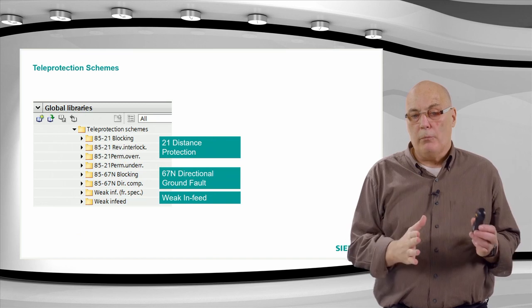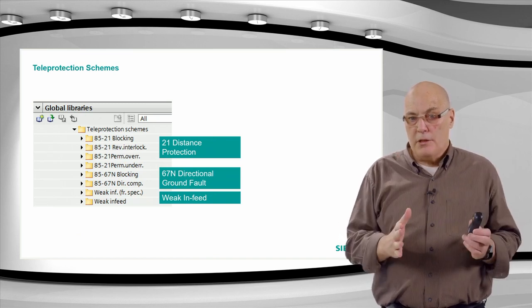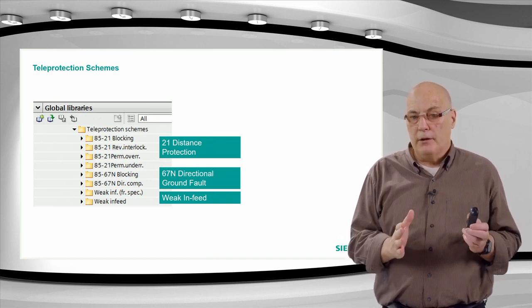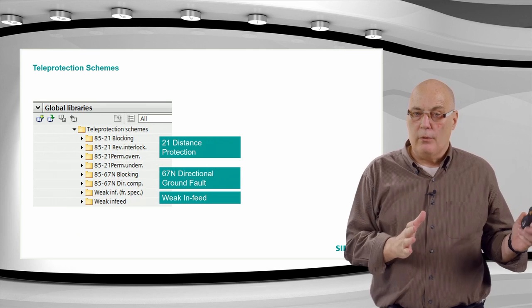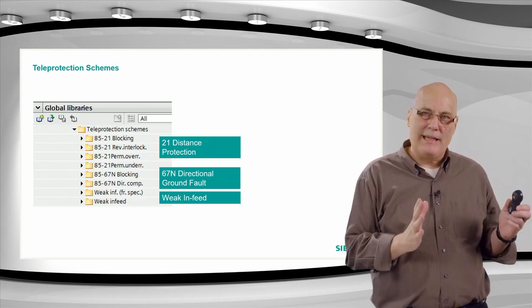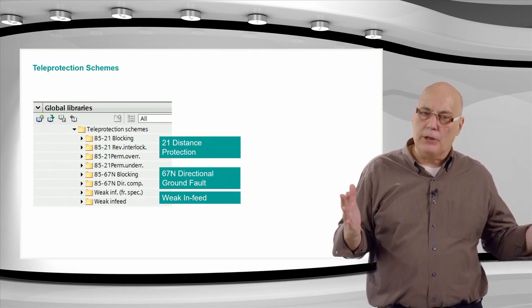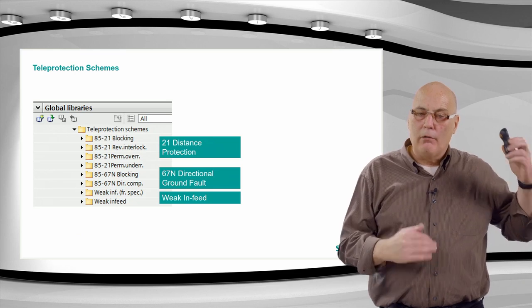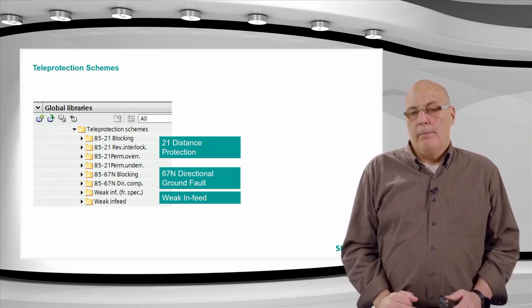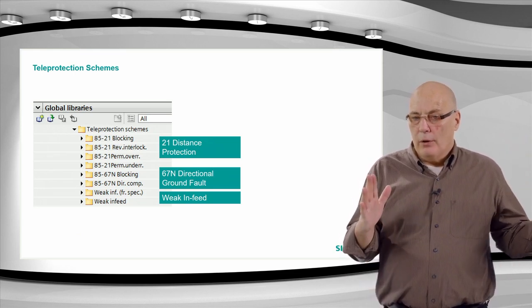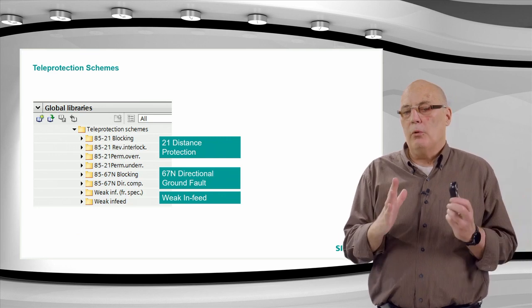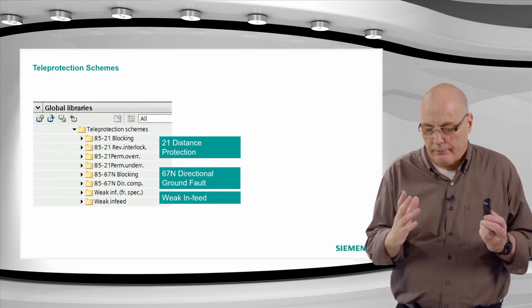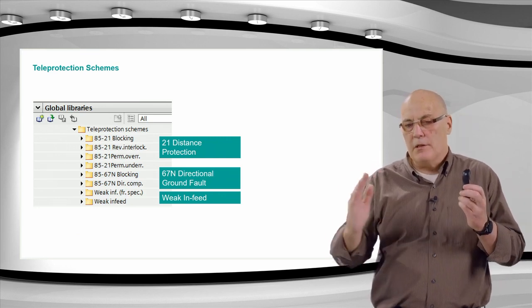Especially, we spoke about it this morning, fault resistance. At some point, if it's a high resistance fault, and that's why we sometimes refer to 67N as high resistance fault protection or high ground fault resistance protection, then it goes beyond what the distance protection should be set to. Remember, we don't want to set the resistance reach of the distance zone too big.